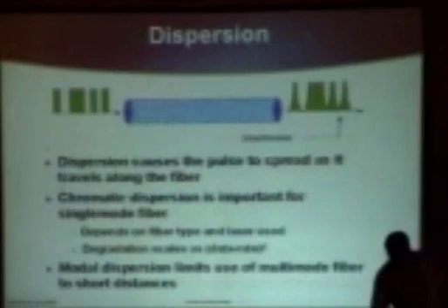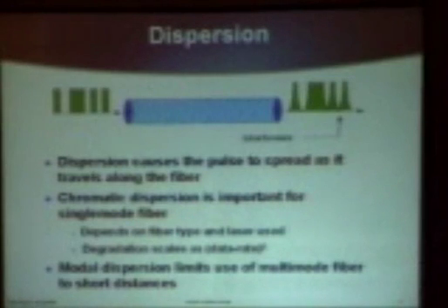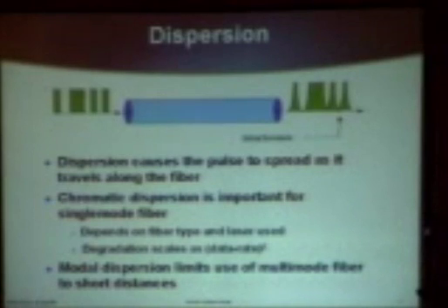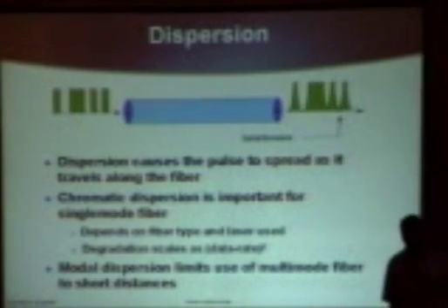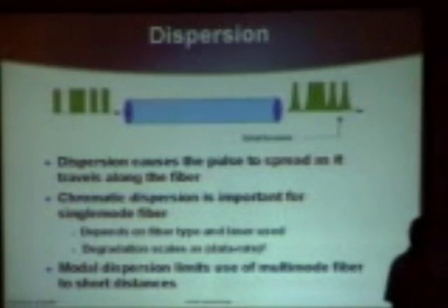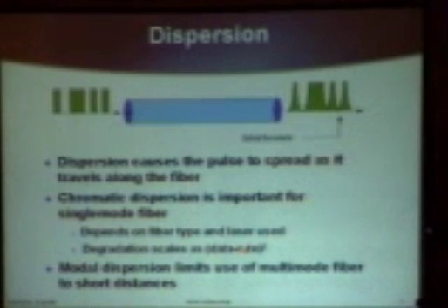So what does this all mean? It's all wonderful, but what it means at the end of the day is that there was a phenomenon called dispersion that happens in the analog transmission of ones and zeros over fiber. You put in nice clean shapes, and at the end of the fiber, you get muck out. And it's frequency dependent. This problem goes up like the square of the bit rate. So for slow speeds, at least in backbone slow speeds, OC3s, OC12s, and for the most part OC48s, dispersion isn't a great issue. But at OC192, where our backbones are going now, suddenly this dispersion problem becomes quite important.